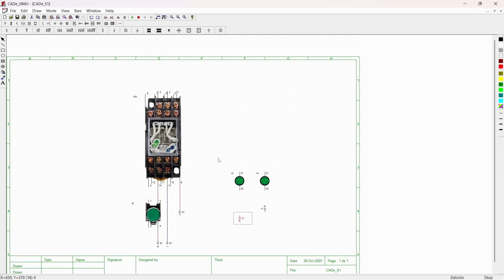Rotate the lamp's terminal up so it's in the same direction. Okay, so I have finished creating a neutral line for the lamp. This is the end source for the lamp. Now I will connect the end source to the first lamp and the second lamp. Next, I will connect the L terminal of the AC power source. I will connect it as follows.